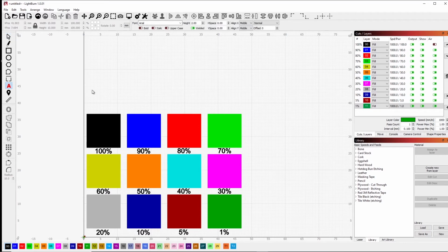And then up on top, we'll want to have some text that says the burn speed. So burning at 1,000 millimeters per minute. And this text can be a little bit larger. That's a little bit too large. Let's try 3 millimeters. And we'll bring that over here. Okay.